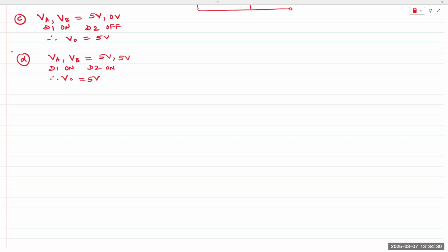No, same. If you apply in parallel, it's going to remain the same. If you apply in series, then they add up. If it's in parallel, it remains the same. If you connect voltage sources in parallel, you can increase the current that is flowing through the circuit. If you connect sources in series, current remains the same, but you can increase the voltage.